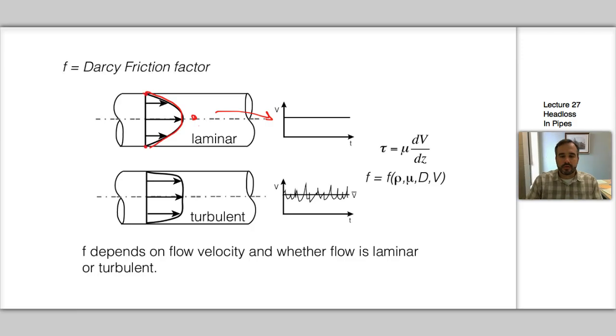Okay? The other type of flow, turbulent flow, is going to have a mean profile that looks more like this shown in the figure. And if I take this same point, like here, and measure it through time, it's going to be really erratic around some mean velocity. But we take that mean. So that black line is that V bar. It's the mean. It's not what you'd see at all points in time, but it is the mean flow. Okay? And you can see, again, there's some shear here near the walls like this, and it's pretty consistent in the middle. It's a very different shape.